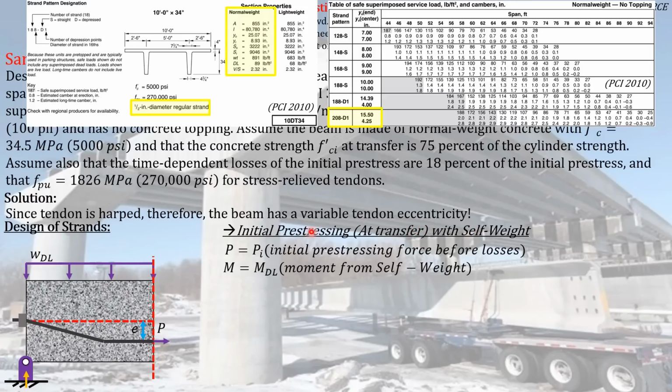So due to those demands, or forces and moments, that you are seeing here, there will be stresses that will be induced in the concrete element at midspan, with a stress diagram which looks like this, with a stress at the extreme pre-compressed fiber equal to FCI and stress at the extreme pre-tension fiber equal to FTI.